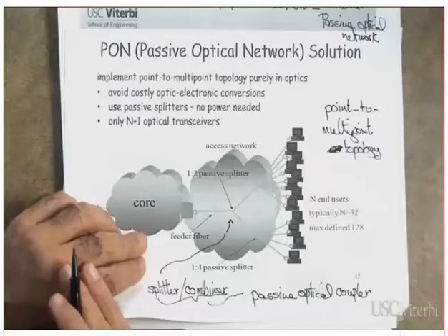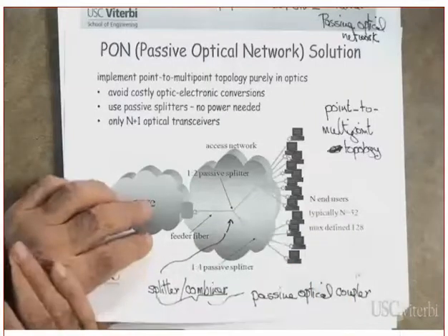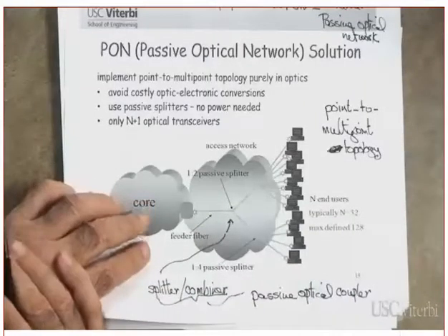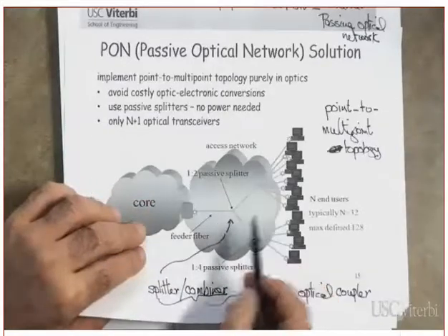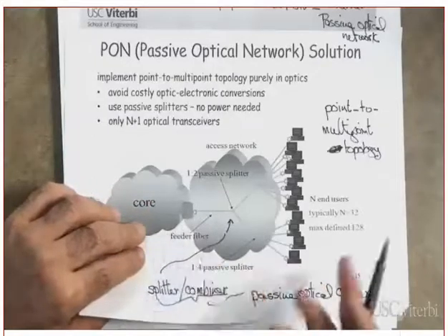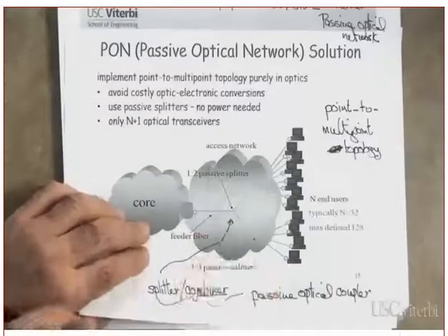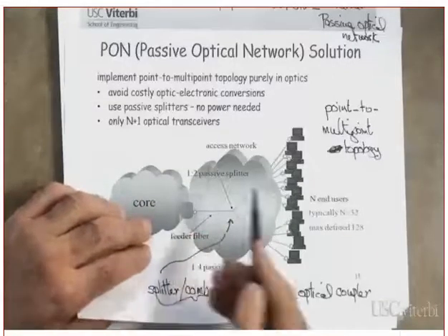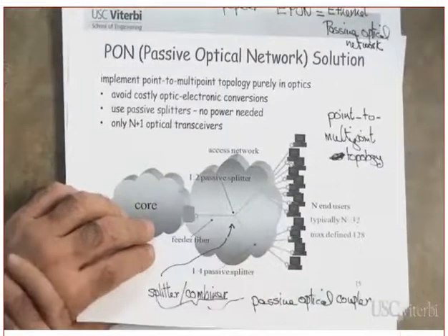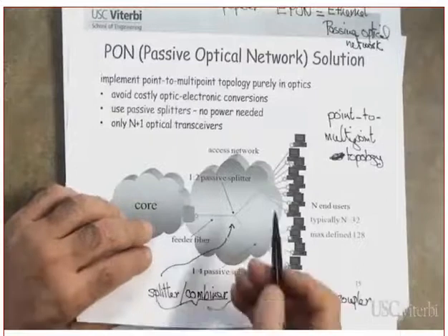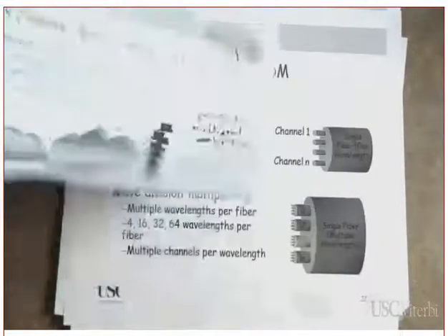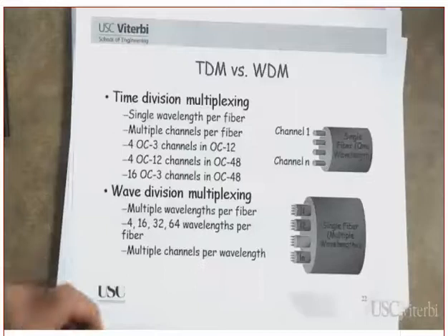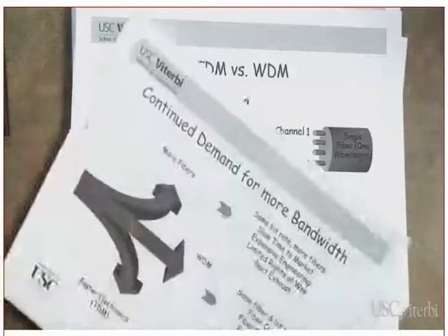It depends on how they deploy the equipment. Remember, if you go to wavelength division multiplexing, you need the right equipment, the wavelength division multiplexer, in addition to optical transceivers. But the good thing is that you are not going to increase the number of fibers. Clear?